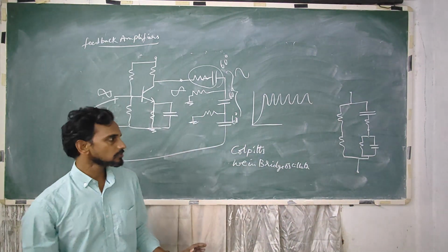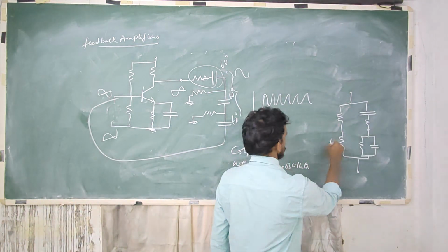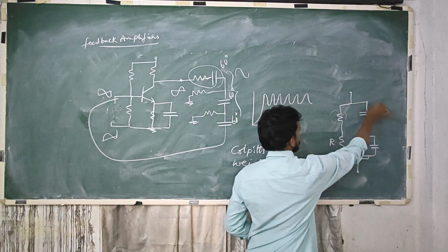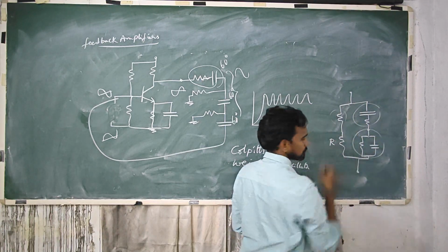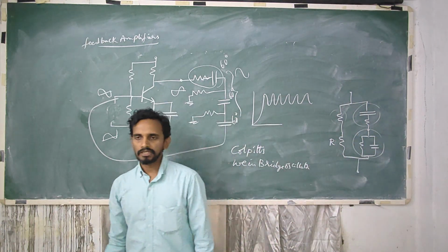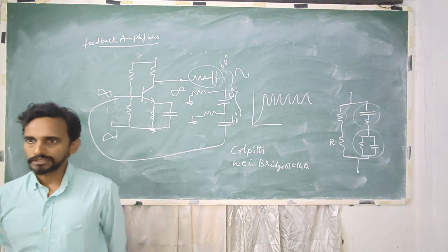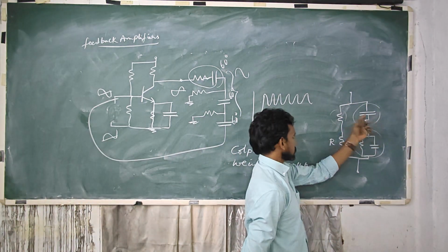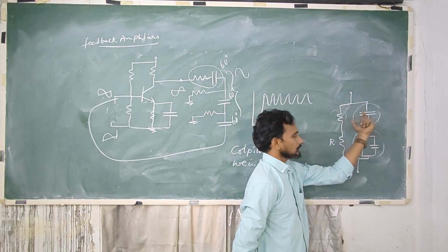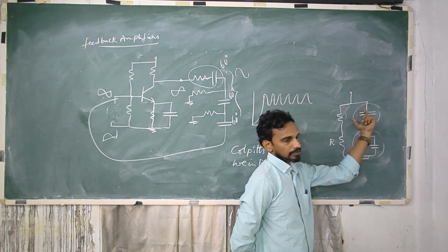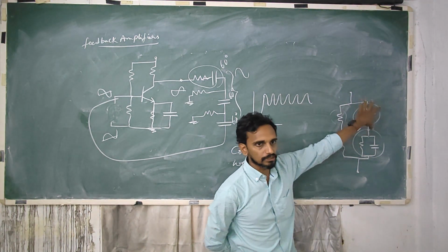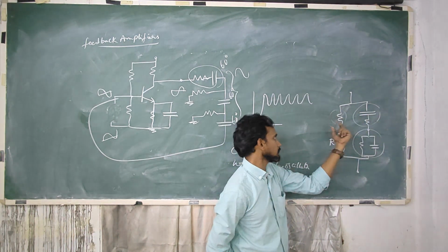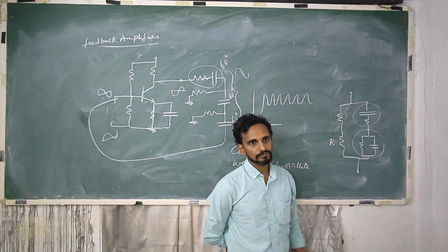So this was used to compare or measure an unknown resistance by using the combination of these RC parallel and RC series combinations, so that the effect of capacitance gets cancelled. I mean, if at all any inductive or capacitive effects occur in the circuit, they will be cancelled out in this component and you get a pure resistance value.